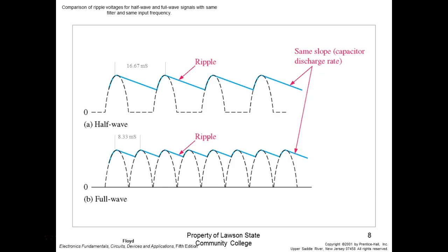If you measure it and it's 8.33 milliseconds, it means your load is probably pulling way more current than the power supply was designed to handle. And so what you're doing is you're exceeding the specifications for the diode, for the circuit, right? So when we say regulation, we mean it only regulates over the span that it was designed to regulate. So a regulator cannot regulate infinite currents, and it cannot regulate infinite voltages, right, without them damaging.